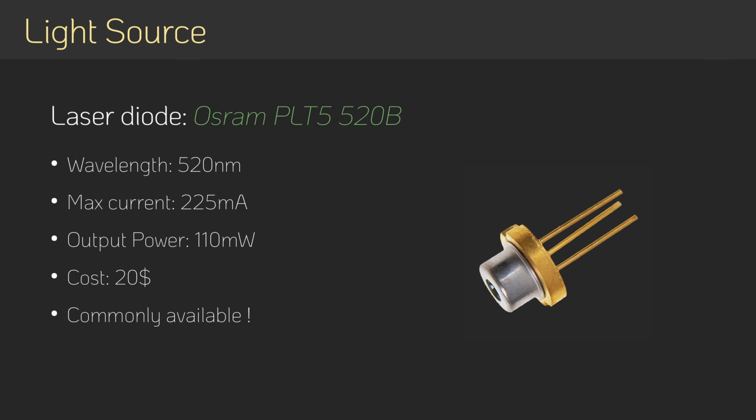For example, the shown green laser diode has excellent coherence length of more than 4 meters right above its threshold current. This is the diode you see used in this video, but I am testing other diodes in the near future and will provide a list of the results. Many low-power red laser diodes around the 5 milliwatt mark are also good candidates, but the small drivers within cheap laser pointer modules should be avoided, as they exhibit large current ripple and reduce coherence length drastically.